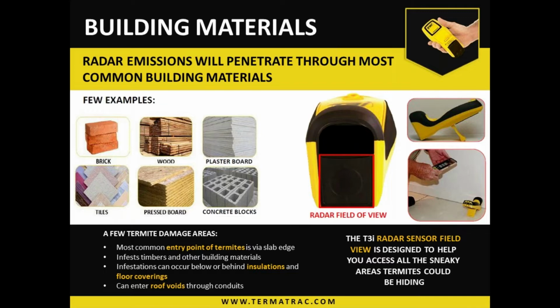Particle boards, so press board, chipboard, MDF, and the like formed boards. It will penetrate through those, no issues that we have come across. Plasterboard, yes, it'll certainly go through that. With timbers, the biggest thing that affects penetration is the density and thickness of timbers. So obviously softwoods, it will penetrate more successfully and deeper within that type of material.